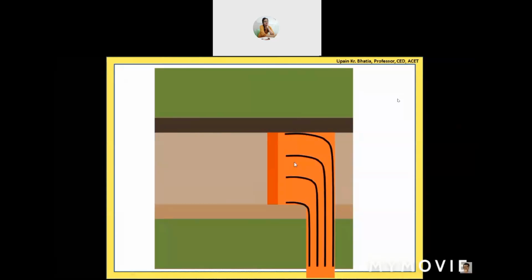They are low height walls, very thin walls, and the top level of these walls is a little above the canal bed level. What you see here is that the gap between the walls is very high, and here the gap between these walls is low. We can provide intermediate walls also, which may not run up to this end, but are provided in intermediate positions and run up to these points only, here, here, and here.